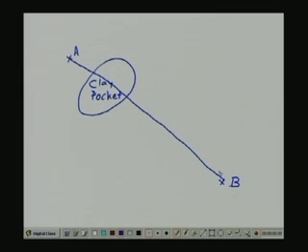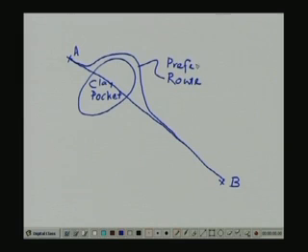As I was mentioning, clay pockets are normally notorious in terms of posing maintenance problems over the course of the project life. So these things are normally avoided, and a route that might be selected may be like this. So this is a preferred route perhaps, whereas this was the shortest route.